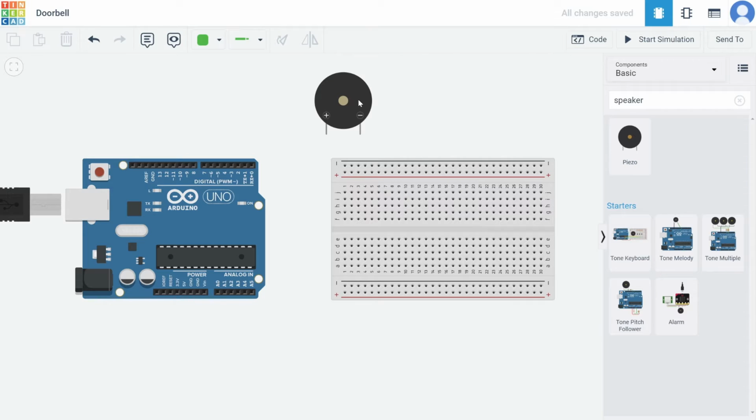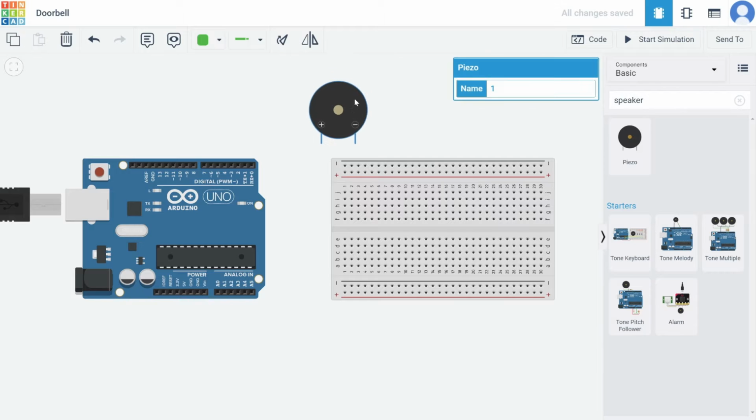Now, when you're using the actual Arduino kits, you should make it on Tinkercad first, but after that you can make it on the real kits if you like. And just a few things. Number one, this is a passive speaker that we're using, not an active speaker, and we'll talk a bit more about that later. But in the kits, make sure you get the passive speaker. The second thing is that the speaker will sound much better in real life than it does on the simulation. It really doesn't sound great, but just bear with it.